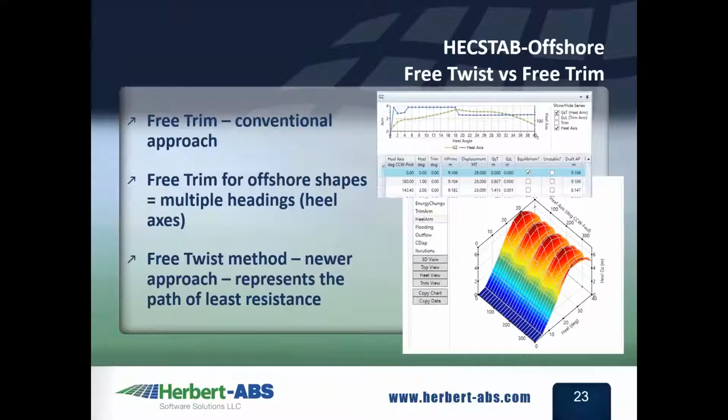The free twist method is the newer approach, and it represents the path of least resistance, where it will allow the vessel to rotate and find the natural rotation as you apply a moment to the vessel, how it would actually rotate as well as heel over.